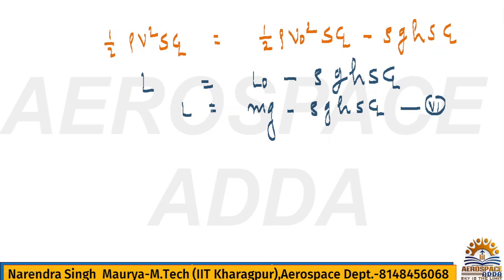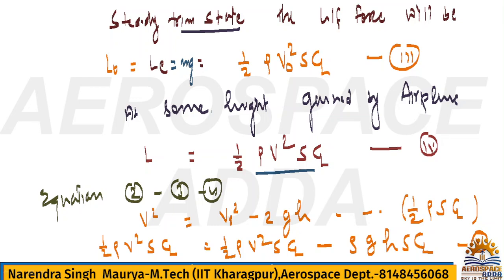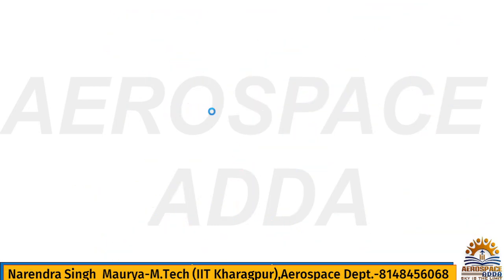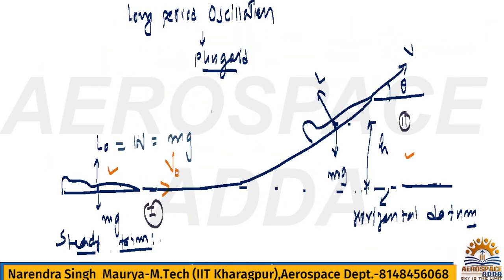Now for this particular diagram, if you go back and check this diagram, theta is basically given from the horizontal. This value is given from the horizontal, theta will be this one. If you check the vertical value, if this is theta, then definitely from the vertical this will also be theta. So this is nothing but L cos theta. So the vertical lift force is nothing but L cos theta. The vertical component will be L cos theta, right?